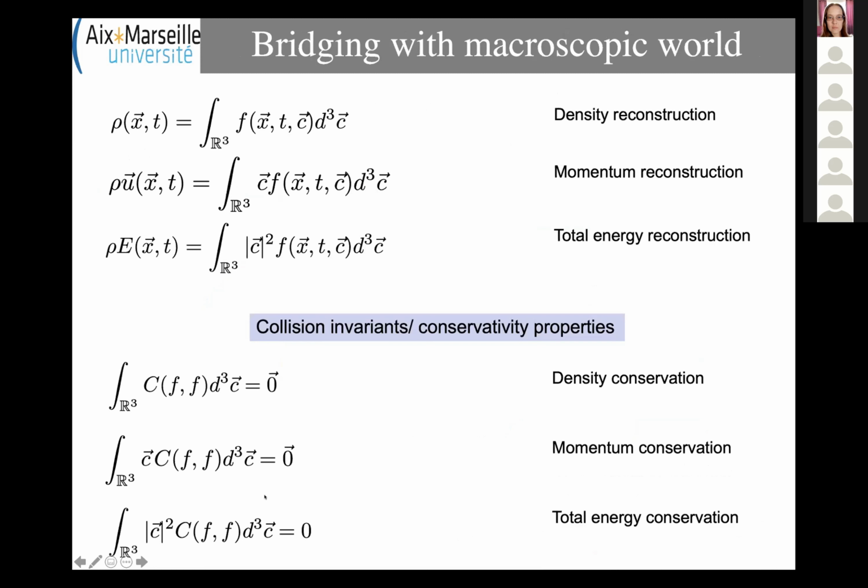But it's not trivial, meaning that after that, of course, we are dealing with numerical methods, so there are some discretization errors. And in Boltzmann, in LBM, the kind of discretization error you have to deal with comes from these things. Because if your set of distribution functions is not chosen in a good way, you are not going to compute, for example, all these integrals exactly. And then you have to deal with errors.